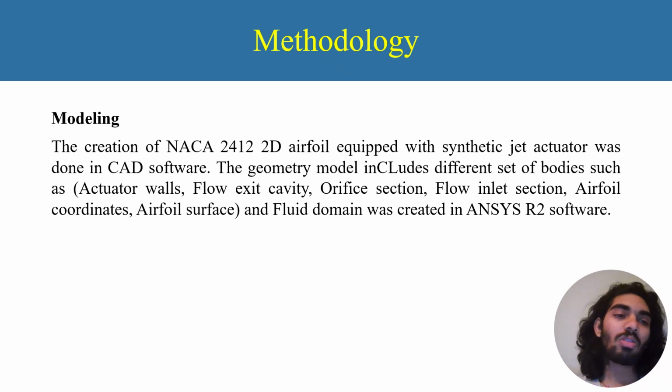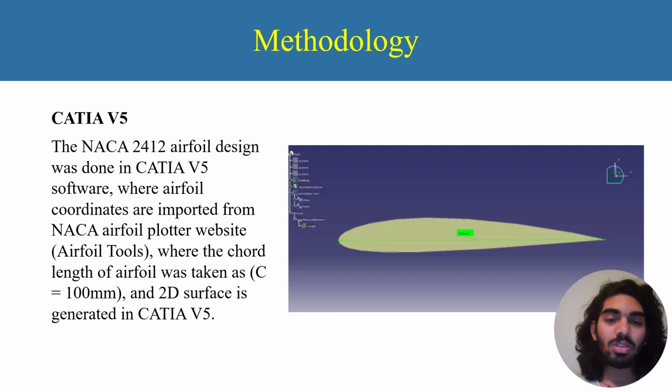For the design, I used NACA 2412 and designed it in CATIA V5. This is the one which I designed in CATIA. I imported the coordinates from the NACA airfoil plotter into CATIA V5 with a chord length of 100 mm, and generated a 2D surface using CATIA V5.